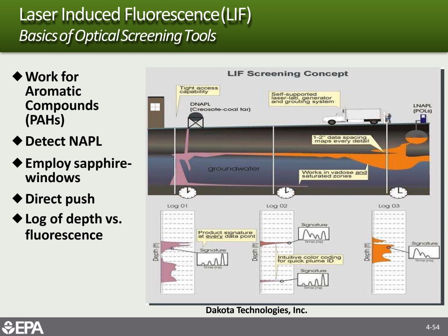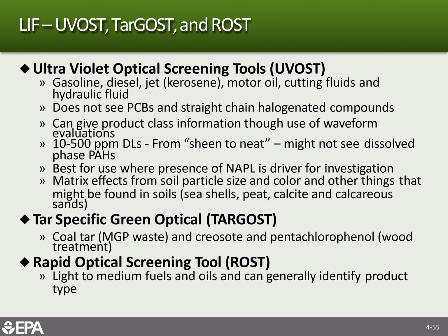And when you push it through, depending on the compound, you get a different reflectance, at a different wavelength. So whether you're pushing through what might be petroleum as an LNAPL or a DNAPL of creosote, you need to have a different tool and you'll get a different response, but all that is understandable with these particular tools.